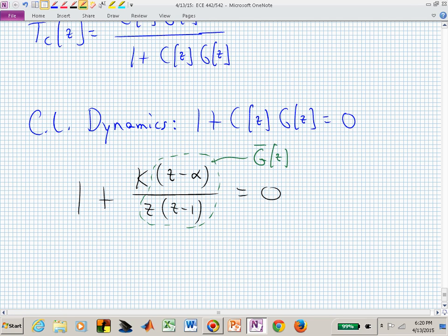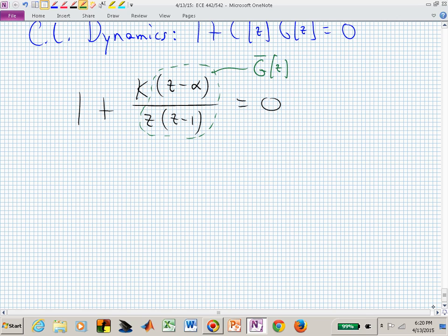What is fixed and what is not fixed so far in that PI controlled system? Are your open loop poles? Can you mess with those? No, they're fixed. One is at the origin and one is at z equal to 1. What you do have the ability to adjust is that real 0, the alpha value. Any suggestions on where we might locate that alpha?